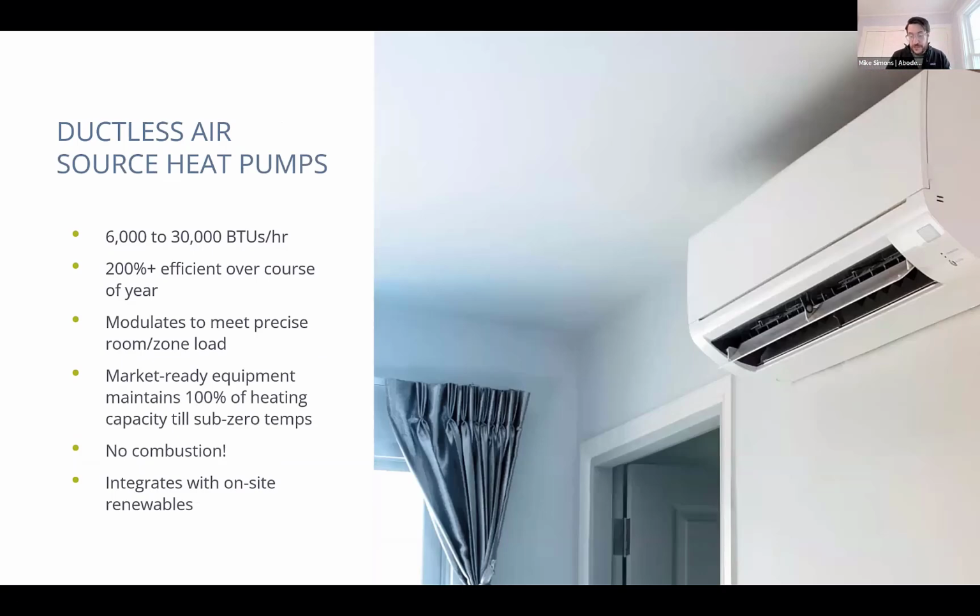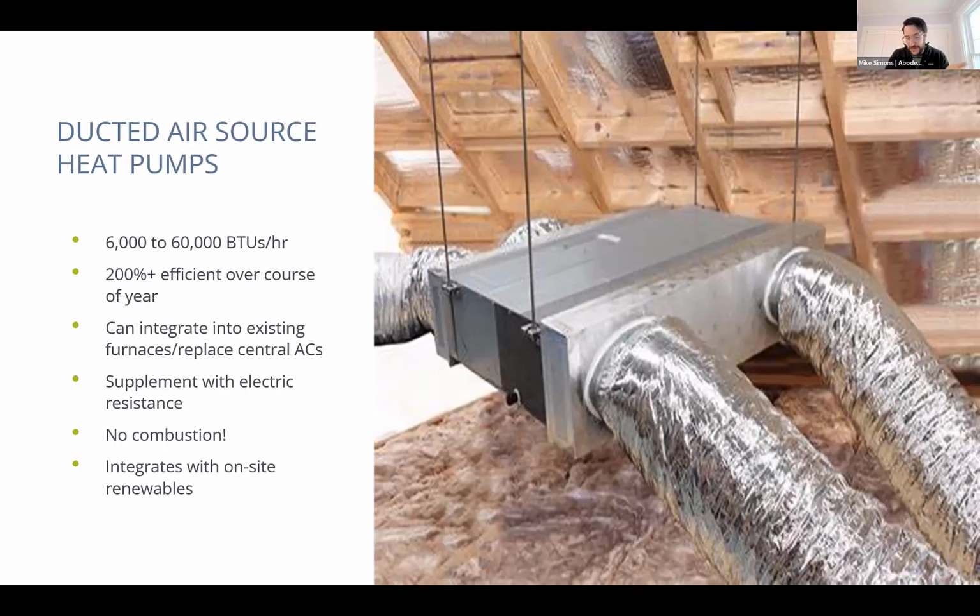Versus with ductless units, where oftentimes they're in a room and it gets the room to the set point temperature and then cycling can be happening. So ducted air source heat pumps, as long as the budget allows, is usually the right way to go when people are trying to electrify.